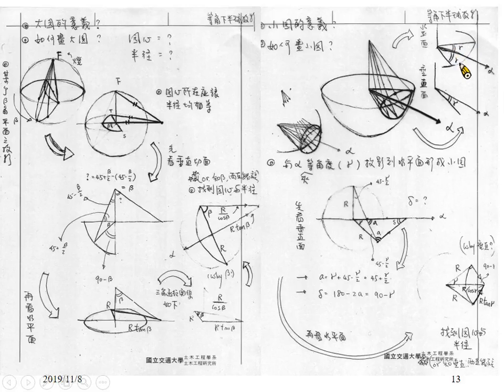Okay? If you transfer it into vertical plane, you can understand this plane will have the same angle between this vector and the horizontal axis. And this gamma can project to the vertical plane like this, and project to the horizontal plane like this. According to the geometry for this and for this, you can define the center of the small circle and define the radius of the small circle.